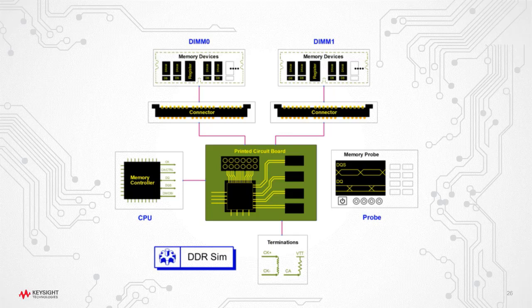Oh, great. Yes, the short answer is absolutely it can be. All you need to do is provide another block connection into the PCB that's representing the VRM behaviorally, and then likewise your PCB should be extracted with the decaps already as part of the EM simulation.